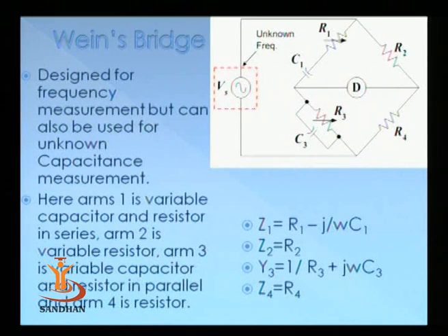So this is what I have planned to discuss as AC and DC bridges. The most important thing for the bridges is the measurement technique. The measurement technique of all the bridges is null detection. So this is basically a loadless kind of measurement. It does not extract any voltage from the measurement. So this has very high accuracy of measurement. So this is all about bridges. If anybody has any questions, they are welcome.